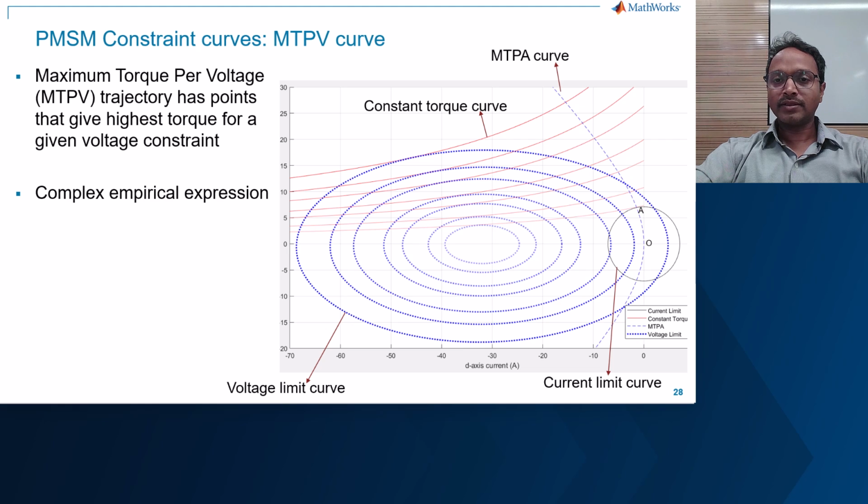Not all the motors are designed to have MTPV region of operation. These are the motors that are specifically designed to have either weaker magnets or high current limits. These types of motors theoretically have infinite maximum speed, only limited by mechanical limits or frictional torque limits or thermal limits. We will look at these special motors' controls within this MTPV region of operation.